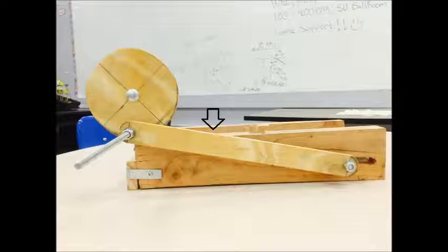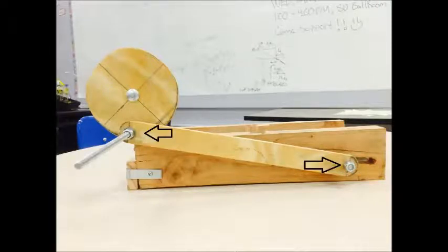However, we were surprised when we found that the stress was well in the 900 range, and our stress was at 23.2 on the actual coupler. This resulted in a huge safety factor well in the 200s for our device. For the bolts, we used the bearing stress equation and calculated both safety factors to be over 3, which corresponded with our desired safety factor of at least 2.